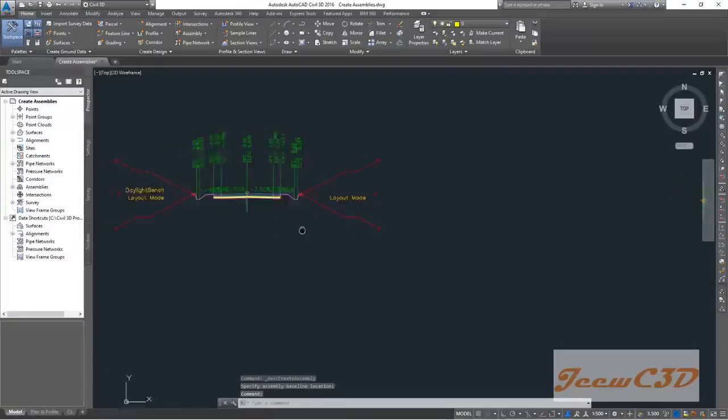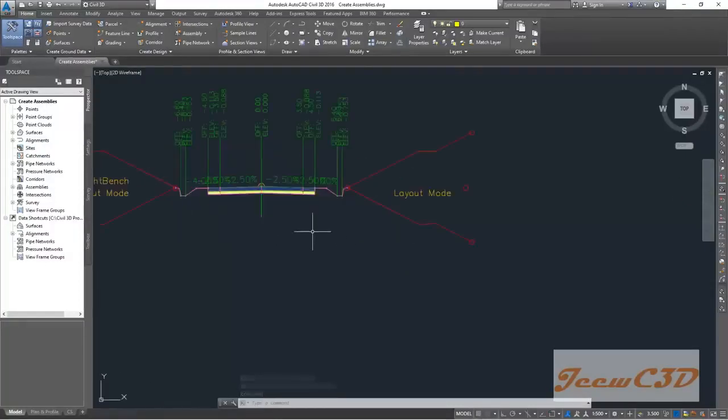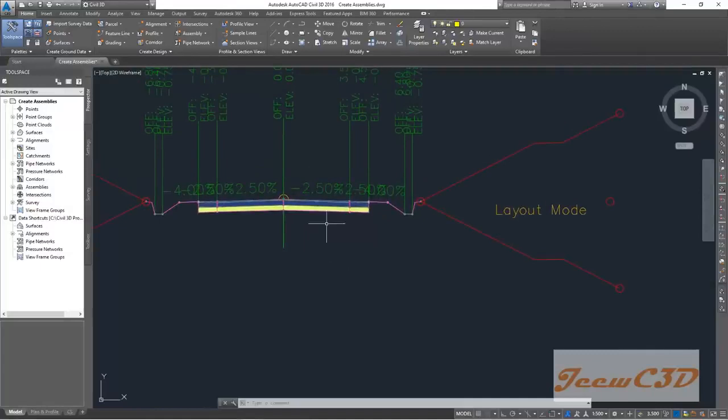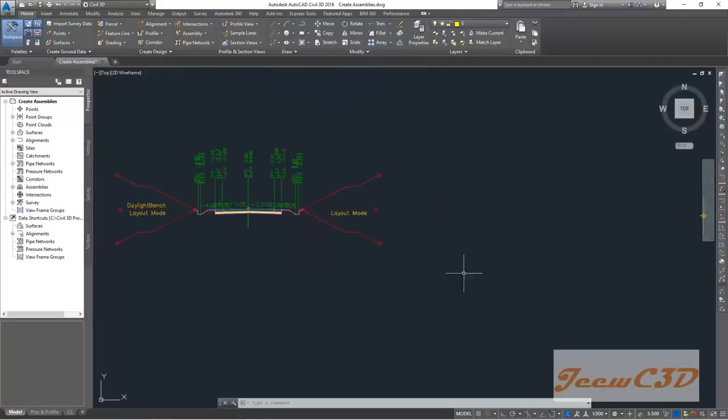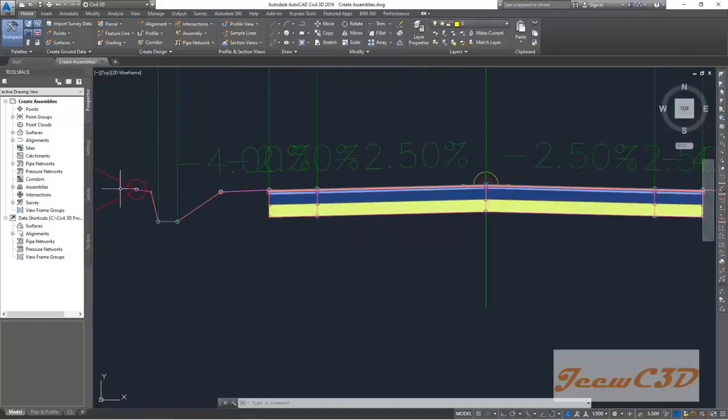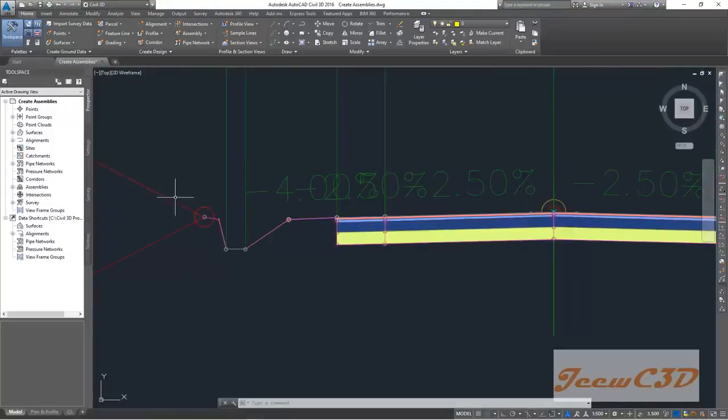In the concrete drain assembly also, you will be having all these three sections: plane, hard shoulder and soft shoulder. So what I can do is I can copy these things to this assembly, except this drain part, earth drain part and daylight part.